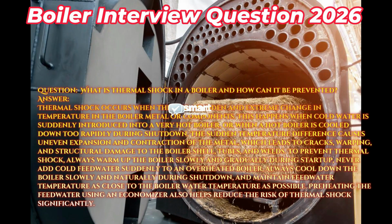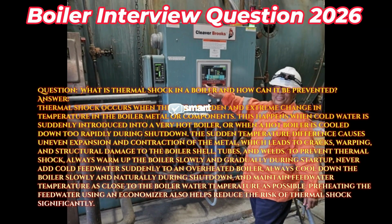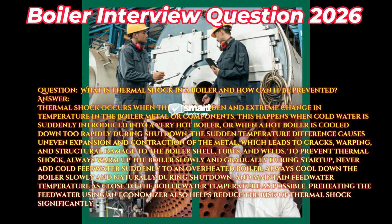Always cool down the boiler slowly and naturally during shutdown, and maintain feed water temperature as close to the boiler water temperature as possible. Preheating the feed water using an economizer also helps reduce the risk of thermal shock significantly.